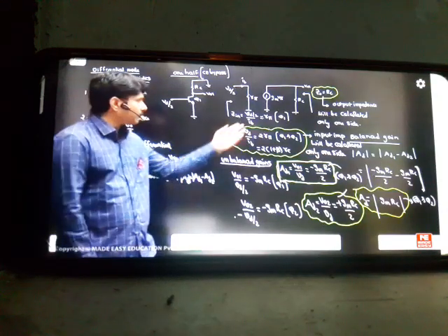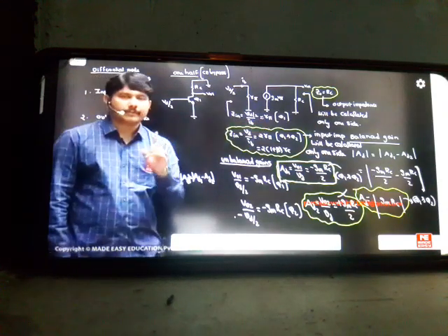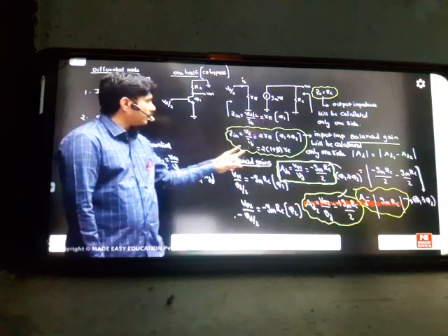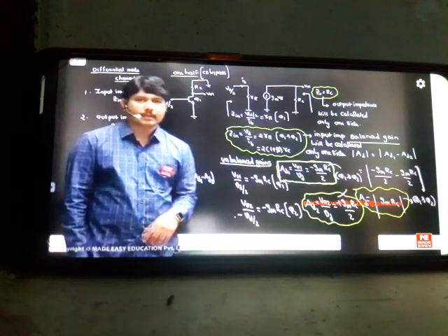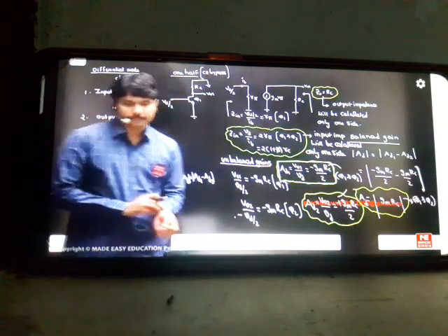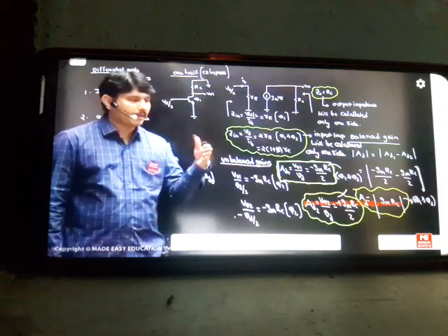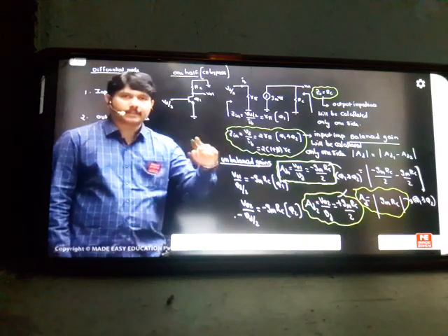Rahman, today the confusion is here. For one circuit it is only R pi. But if you consider both, the formula has changed. 2 has come there. VD by IB for two transistors became 2 R pi. Already clear from the previous example: the base current from the one R pi goes to the second R pi. So the impedance will be in series, 2 R pi.